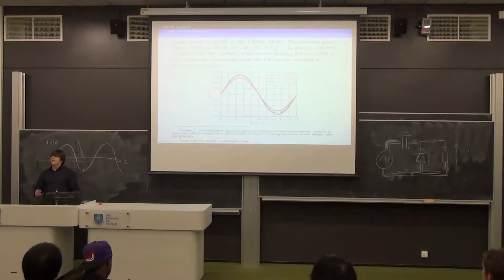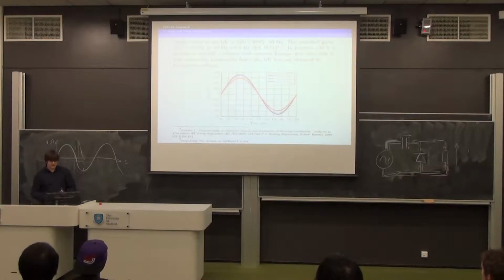Get a plug, take the back off, plug it in, switch it on, get a meter, and just put it across the live and the neutral on AC. Make sure you know what you're doing first. You'll get a measure of the mains at the point where you're taking it off. And it varies quite a lot actually. One thing you can do is do it downstairs, run upstairs, turn your power shower on, run back down and have a look.